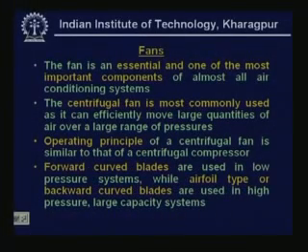Normally, forward curved blades are used in low pressure systems, whereas the airfoil type or backward curved blades are used in high pressure large capacity systems. Compared to forward curved blade centrifugal fans, the airfoil type or backward curved blades give higher efficiency.